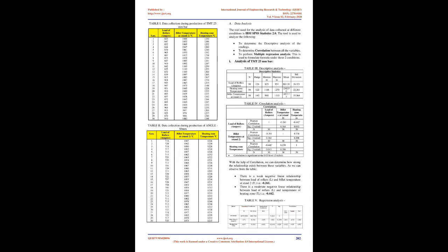3. Data collection and analysis. The primary data is collected directly from the fixed-type radiation pyrometer installed near stand 2 of the reheating furnace and mill operation. The variables measured in the process of data collection are as follows. Temperature of billet at stand 2 in °C equals Ts. Temperature of heating zone in °C equals Th.